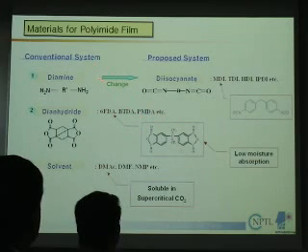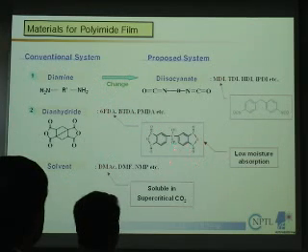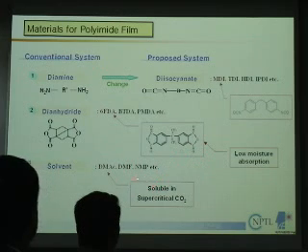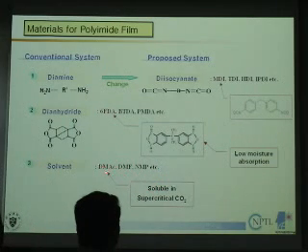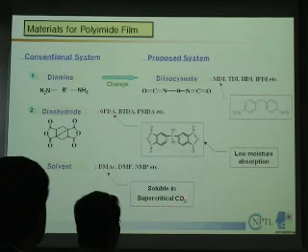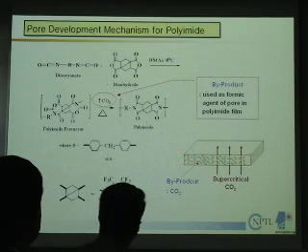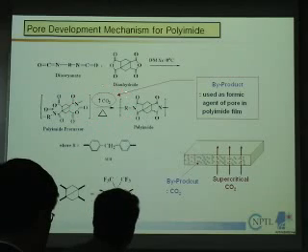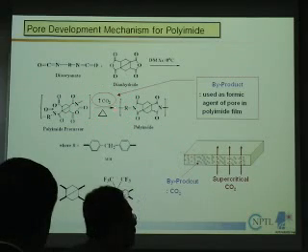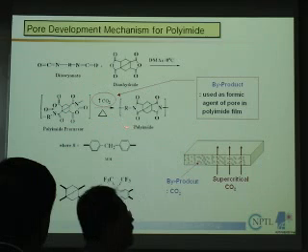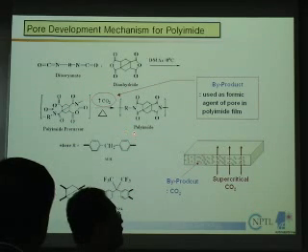This is the conventional way of making polyimide polymers. We use DMAC as a solvent because it is soluble in supercritical CO2. And we use this system because we need some kind of CO2-generating combination, since we use this as a foam generating material, a foam generating side product.